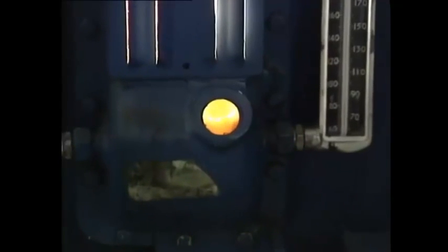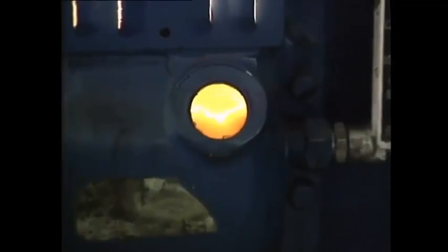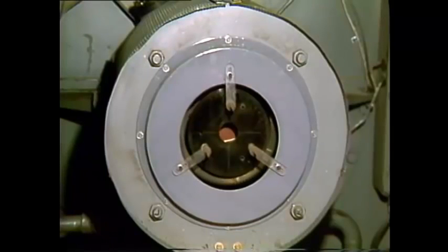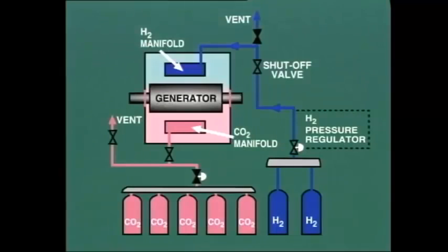This entails running a low-pressure oil pump to circulate oil through all of the turbine and generator bearings and starting the hydrogen seal oil system. The turning gear motor can now be started to rotate the shaft at low speed, usually about 10 RPM. The procedure for charging the generator with hydrogen is detailed in the next module in this series.